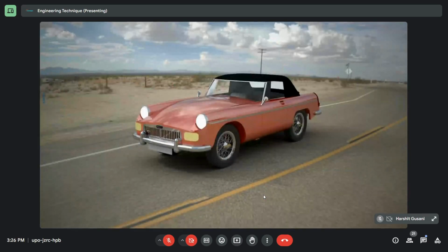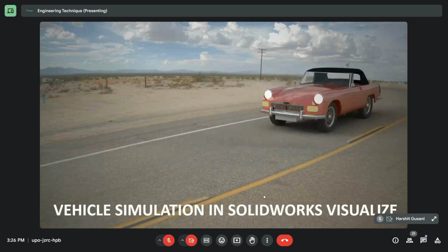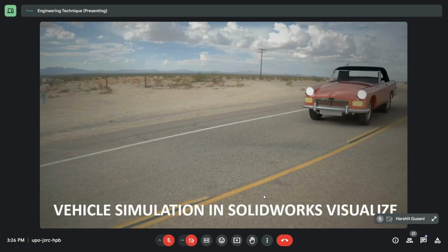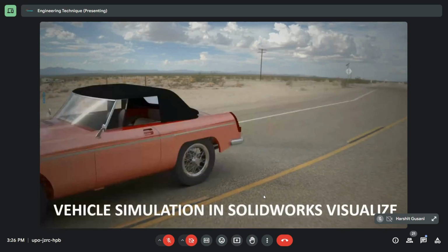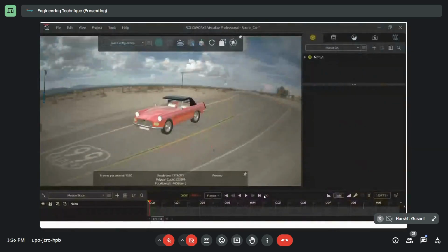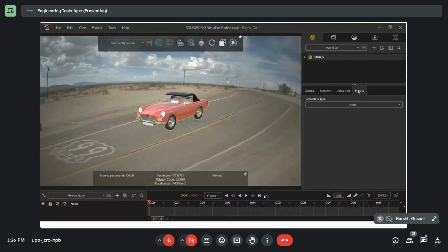So now, next, this is the overview video of a vehicle simulation, which was created in SOLIDWORKS Visualize. I will show you how to create that vehicle simulation. First of all, select the part and go to SOLIDWORKS Physics, vehicle simulation, type vehicle.